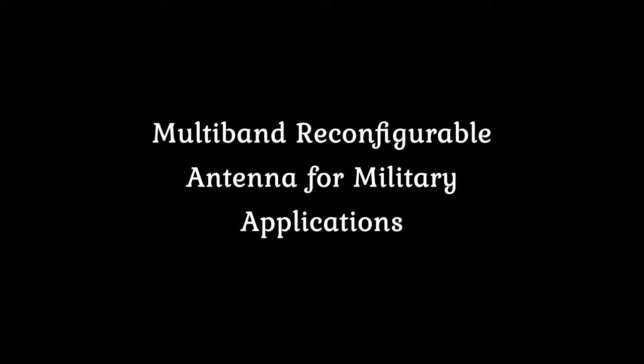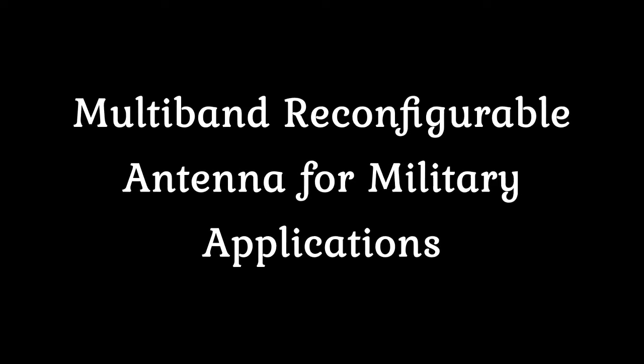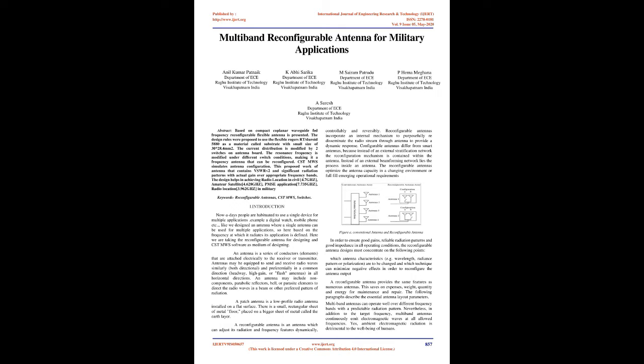Multiband reconfigurable antenna for military applications. Abstract: a compact coplanar waveguide fed frequency reconfigurable flexible antenna is presented. The design rules propose using the flexible Rogers RT/duroid 5880 as the substrate material